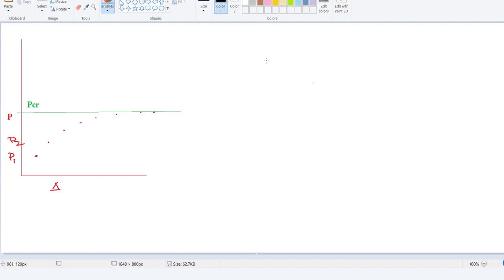There you could see that this is the displacement called the second order displacement under any load, and this is the displacement for the conventional analysis, or we call it the first order analysis. This is roughly amplified by the value of 1 over 1 minus Pu by PCR. Okay, this is the multiplying factor.